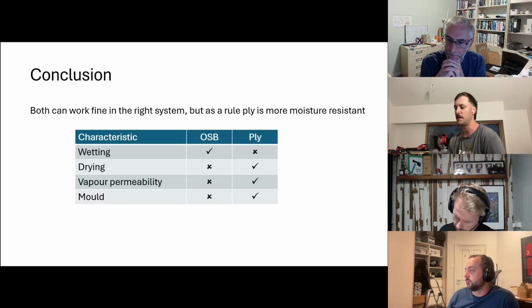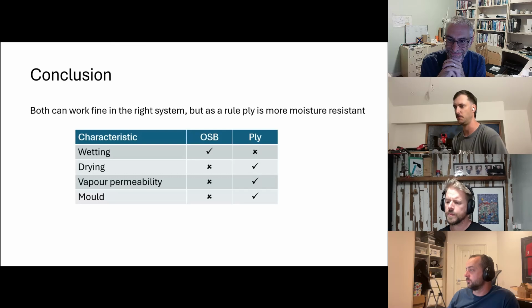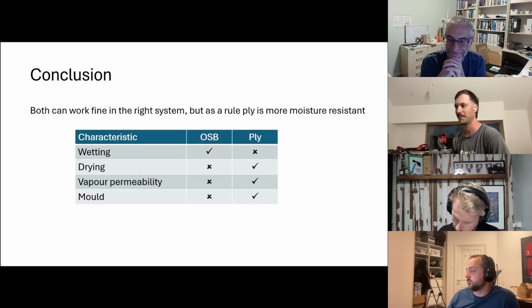That's a side subject, and maybe a subject for another day, but we do all this about ventilated cavities, and we've got cavity closers that have got open areas, and we do for lightweight cladding, and then we go to a brick wall and we've got a 50mm cavity and we've got weep holes down the bottom. That's probably more susceptible to moisture ingress because it's such a porous product, and we just send it and think it's a good thing.